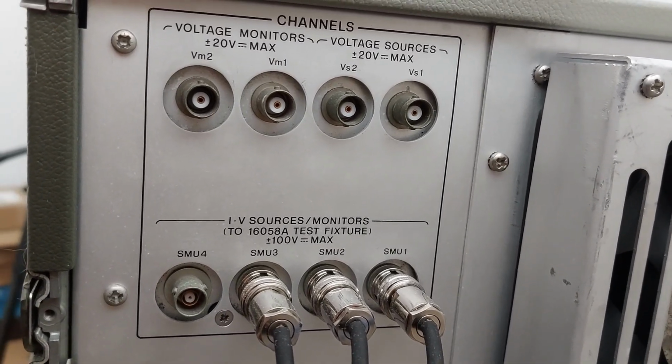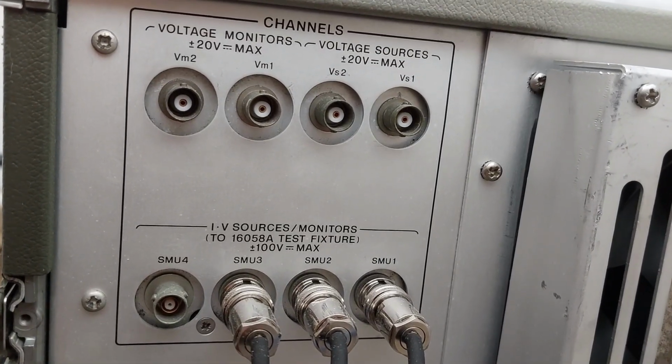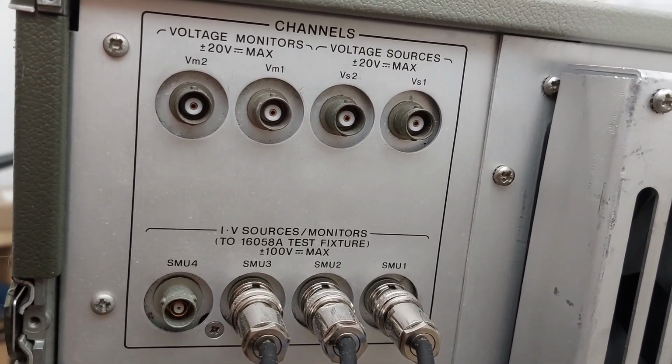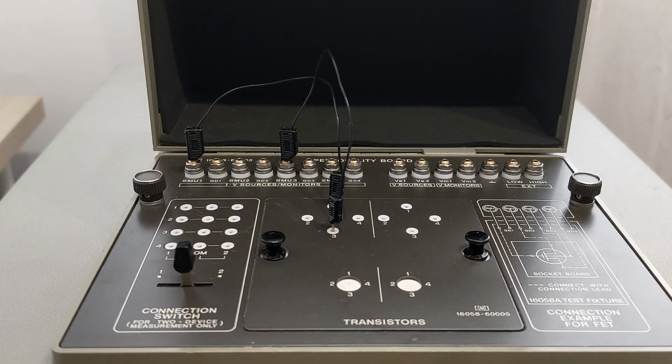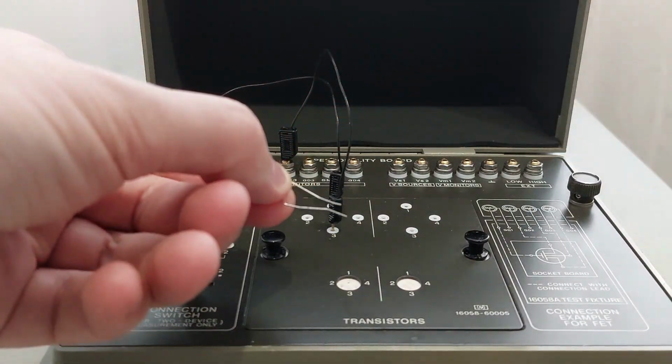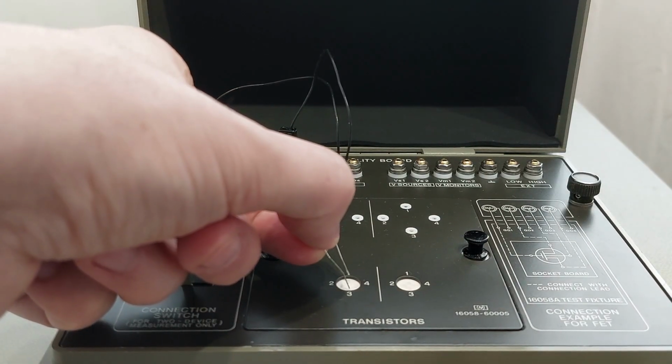To test the forward voltage versus current dependency, connect SMU1 to the diode anode and SMU3 to the diode cathode. I am using this test fixture, but you can use any DIY jig you have. Just keep in mind that without the GPIB-like cable and the original test fixture, the instrument's source voltage will be limited to 40 volts. So connect the diode first. The anode goes to SMU1 and the cathode, or the minus, goes to SMU3.